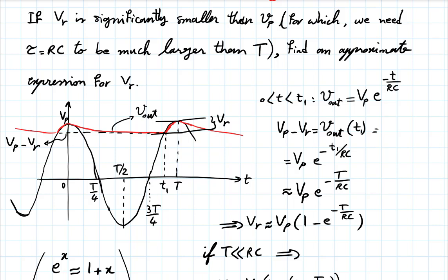Gradually, it reaches its maximum, and the slope becomes 0. The capacitor current becomes 0 in the charging direction, and then it starts discharging in the resistor, and that's when the diode is off. So the diode current is actually at its peak at time t1.